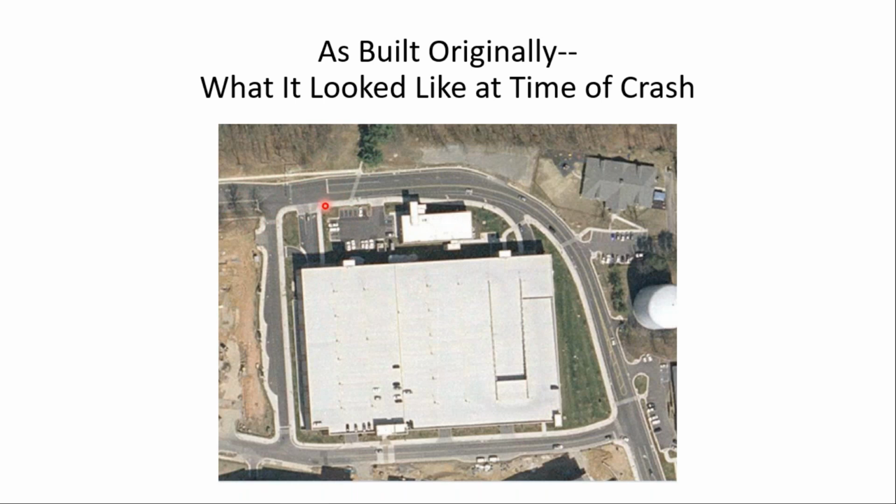And notice where the stop line is for this approach to the intersection. Notice that's a little bit unusual, right? We typically, a crosswalk is downstream of the stop line. In this case, the crosswalk is upstream of the stop line. It's almost like a mid-block crossing, and that's kind of the crux of the case.